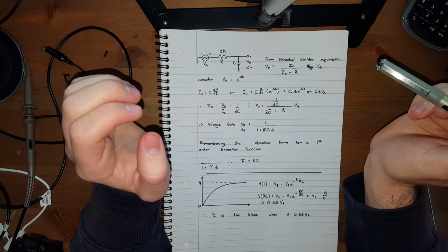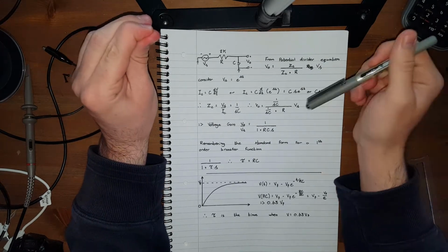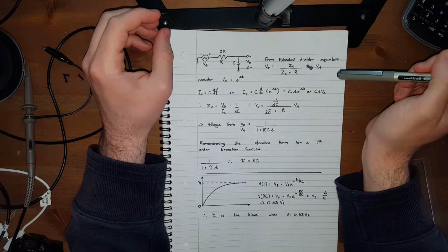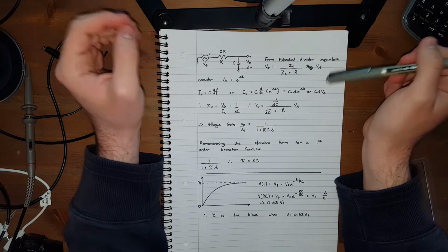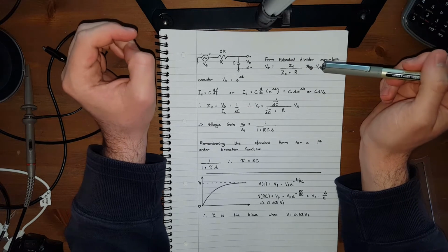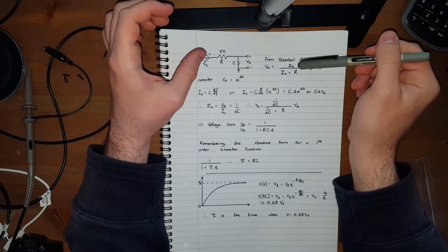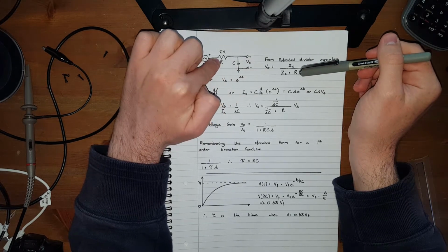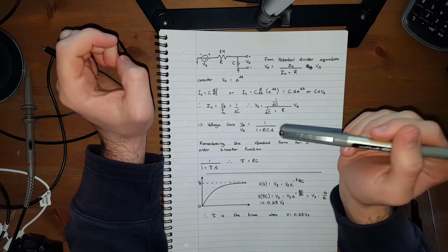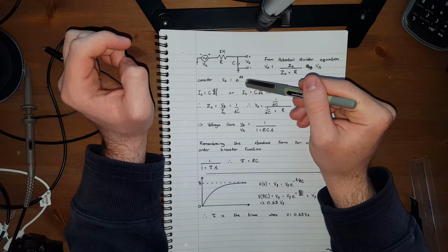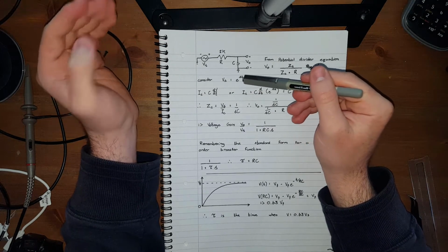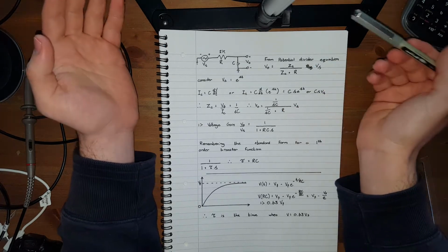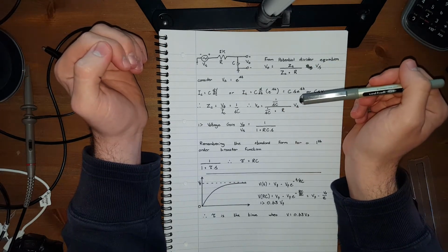In order to understand how we're going to get capacitance from this, we need to derive its transfer function. If you express the output voltage VO in terms of the input voltage VS, the source voltage, we can use the potential divider equation where ZC is the impedance of the capacitor and R is the resistance of this fixed resistor. If we let the source voltage equal a e to the st, where a is the amplitude of the signal, I've set the amplitude to 1 to make things simple.